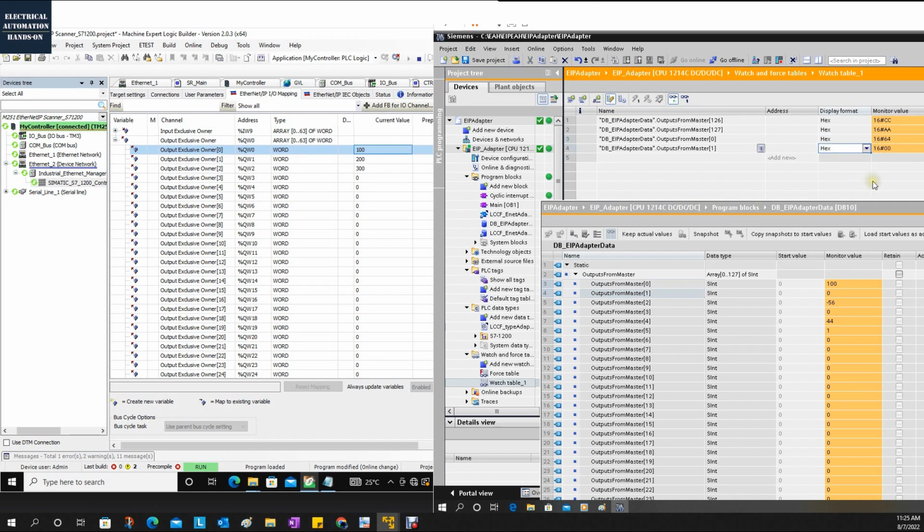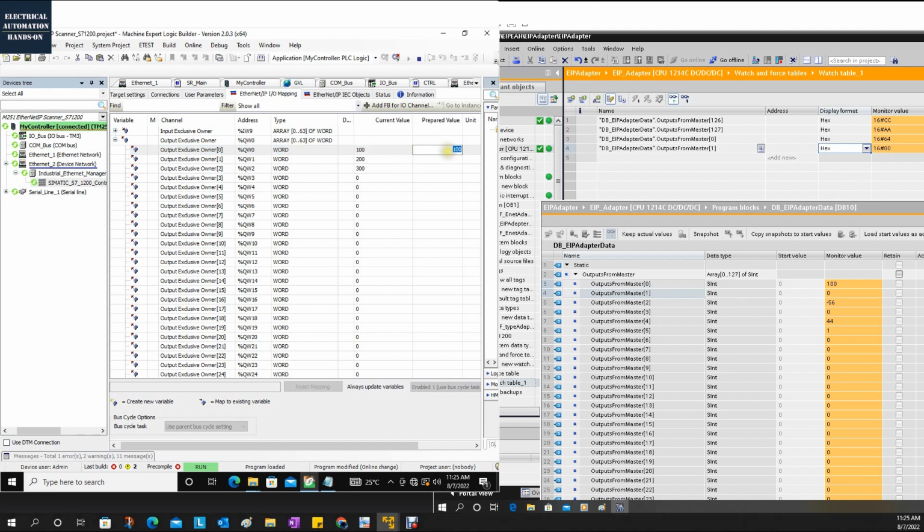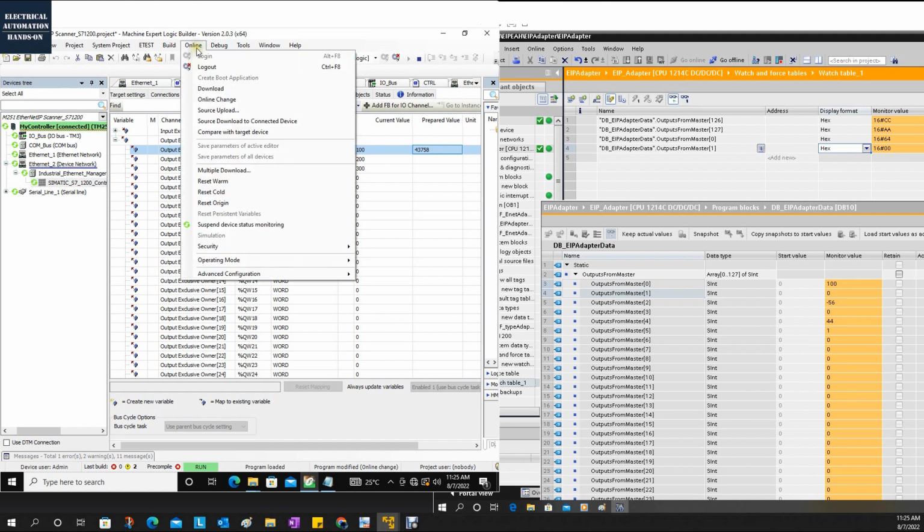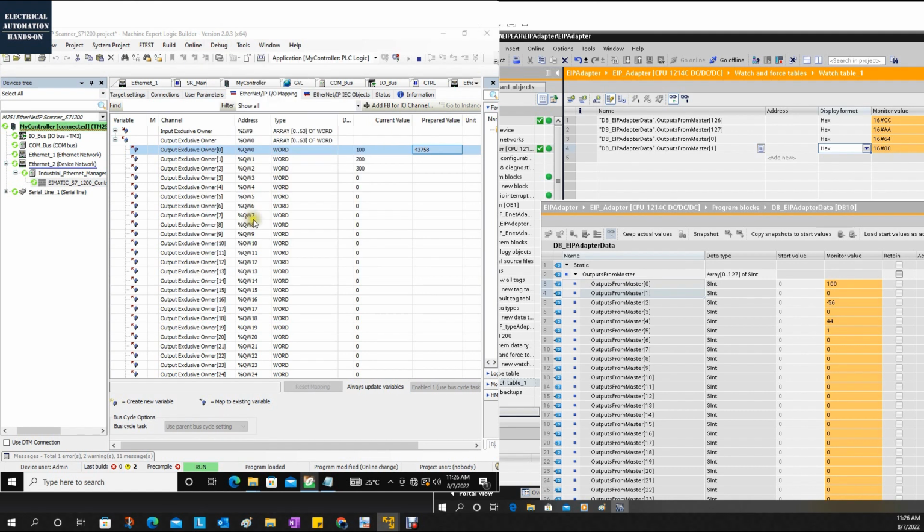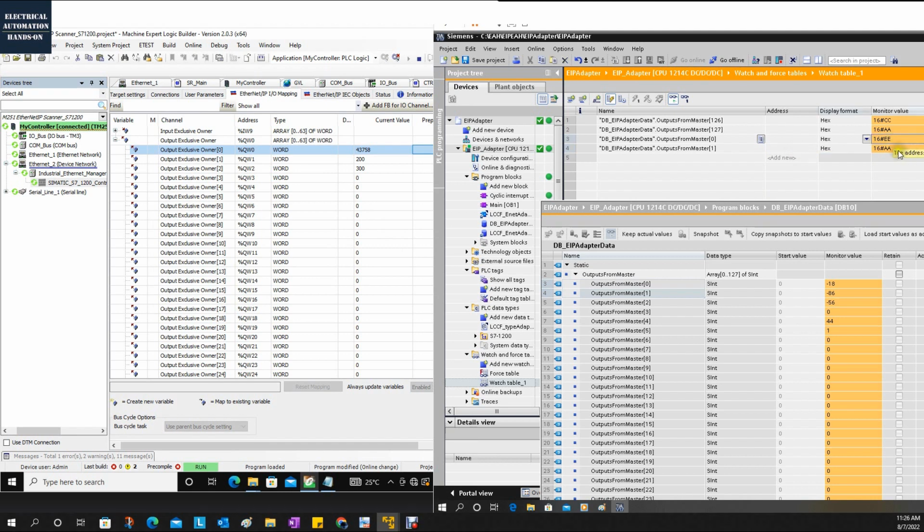So this time for this output, if I type in 16#AAEE and send it out, we will see AAEE. EE comes from the low byte and the AA comes from the high byte. Okay, so keep in mind this low and high byte.